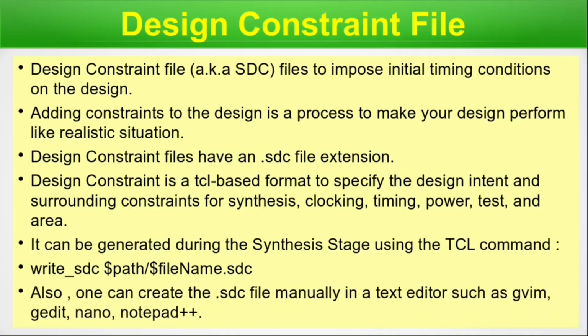Also, one can create the .sdc file manually in a text editor such as gvim, gedit, nano, Notepad++. I don't know which text editor you prefer. You can write in the comments below which text editor you are most comfortable with. Generally all these text editors nowadays have highlighting capability. That means if you are using Tcl, they will highlight the Tcl proper names and keywords in one color and your normal values in a different color. So at least what I can say is that you can write the commands manually and give it as an input to the tool, or you can dump it using the command just mentioned above. I think we are done with this slide. Let's move on.